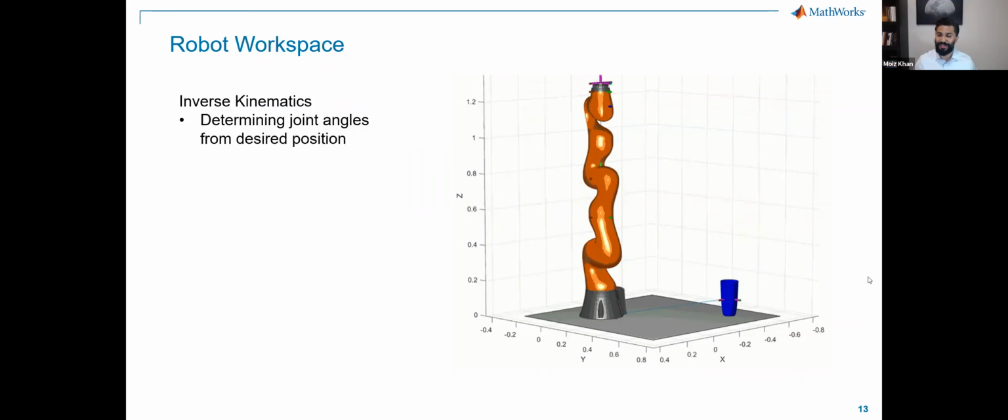Now the other issue becomes that as you start building these robotic tools, how do you get the robot to work properly in your environment? So for those who are familiar with robotics, this will be a very simplistic concept. It's called inverse kinematics. You have some desired trajectory that you need to follow for your robot, and you use inverse kinematics to calculate all your joint angles. So each joint of the robot has a motor, and you calculate the angle that's required to get the robot to do what you want. Very traditional robotics 101.